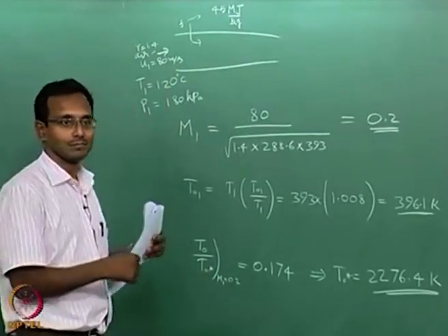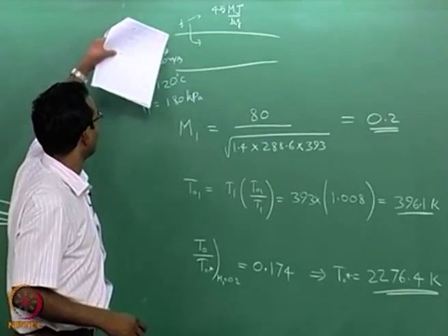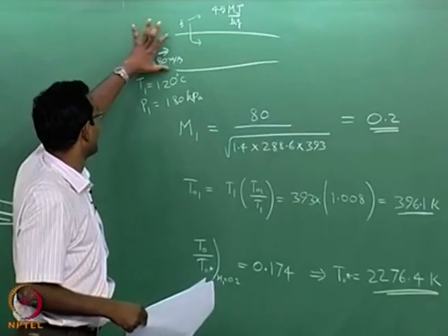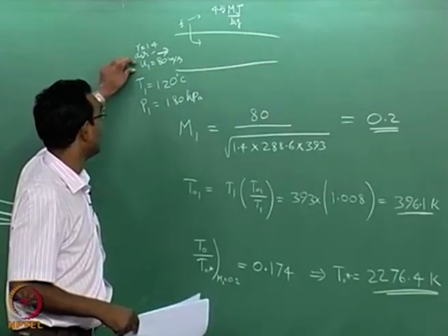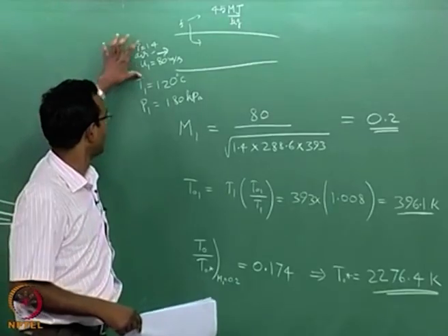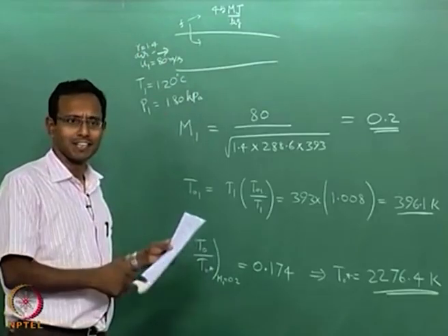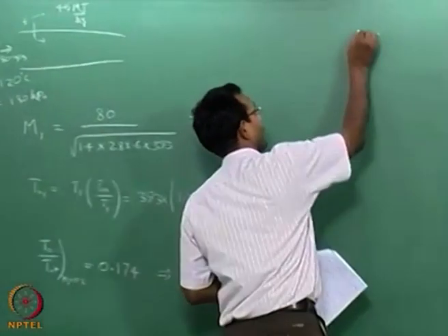Okay. So the remaining thing is just finding out how much fuel can be burnt per mass of air, because we don't know the absolute mass flow rate since they did not give me the area of the duct. If I know the area, I can find the mass flow rate given this information. I know density, I know U, I just need area, then I can find the mass flow rate, then I can find the mass flow rate of fuel required. I didn't give you area, so we won't calculate that right now. So I just need to find Q max.